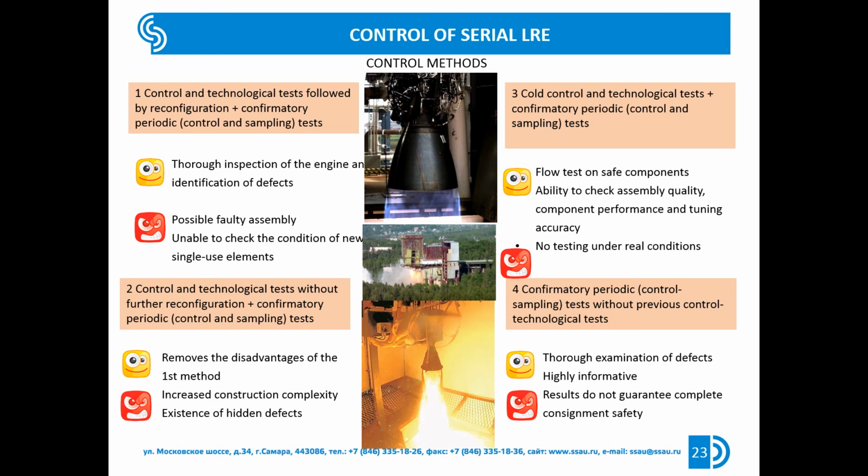They also check the operation and evaluate the performance of pumps, turbines, valves and control system elements, and determine the accuracy of the LPRE tuning in terms of fuel component ratios. A significant disadvantage of these tests is that there is no testing of the LPRE under real operating conditions.